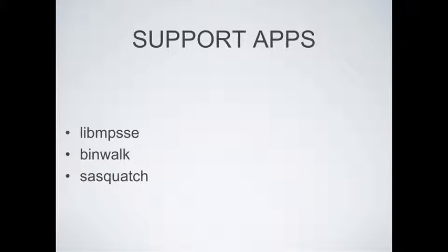And you need to download a couple of support applications. You will need the libmpsse library for interfacing with SPI and I2C devices. You need the library because there is an FTDI chip inside of the little USB cable. It's actually the FT232H, and this helps you interface with the devices so that you can read over SPI.